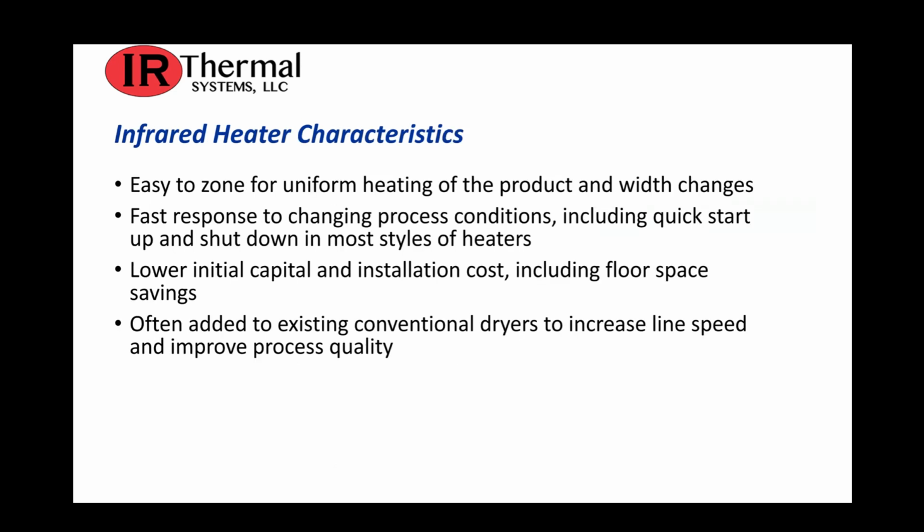So infrared heater characteristics include that they are easy to zone for uniform heating of the product and width changes. They have a fast response time to changing process conditions, including quick startup and shutdown in most styles of heaters. They also have lower initial capital and installation costs, including floor space savings. And they're often added to existing conventional dryers to increase line speed and improve process quality.